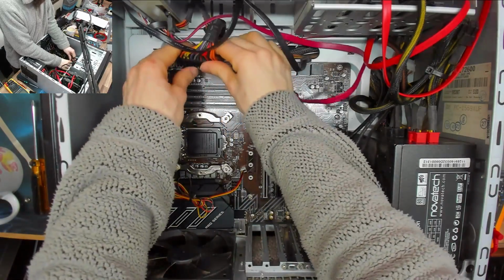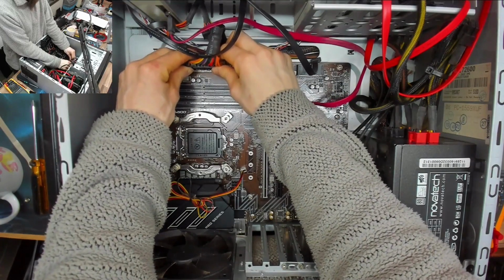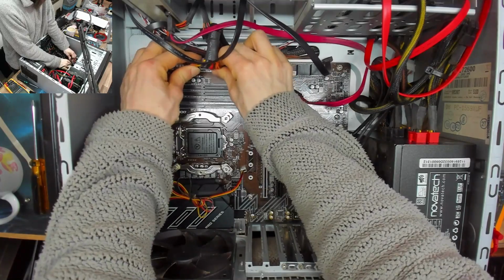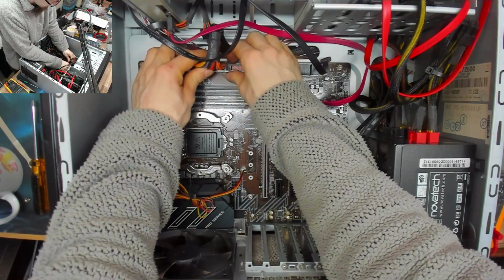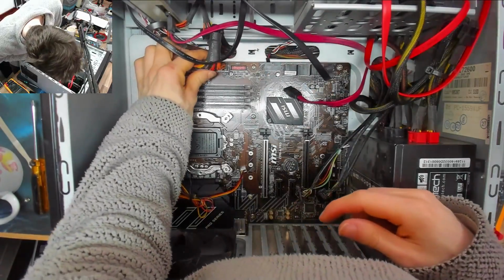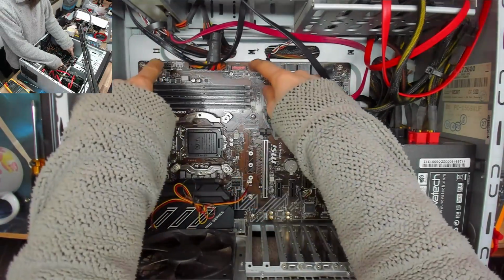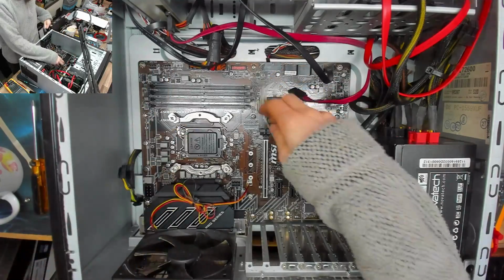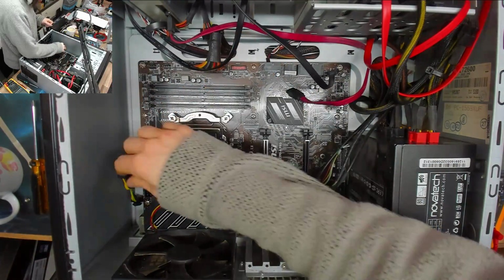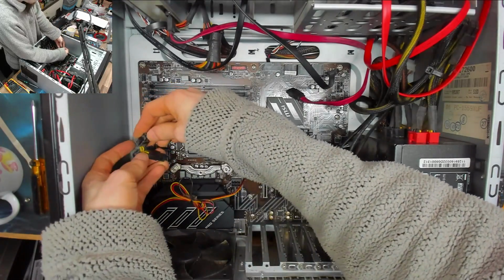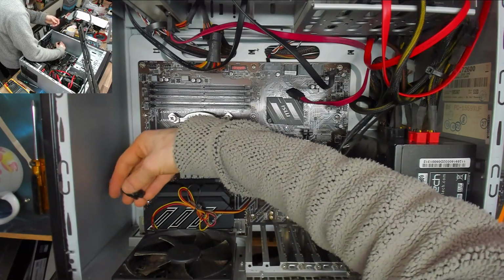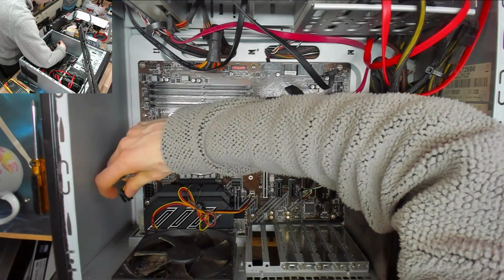Okay, let's hook up all the obvious stuff again. Luckily we don't really need to worry about the cable tidy job in this case, because there's no case window, so we can just shove everything in as and where it falls. Because this motherboard is quite a wide one, it goes all the way out to the end of the standard ATX markers. We've got lots of screws holding it in place, so we don't need to worry about motherboard bending. And unlike the previous board, we've got a nice 8-pin power connector going into our CPU now. None of this 4-pin rubbish.